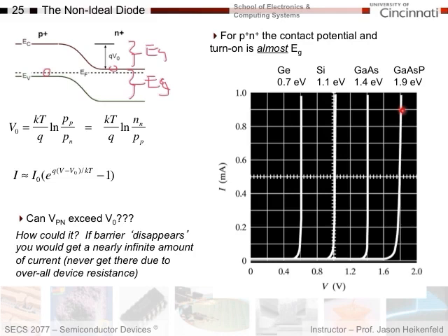And so this shows you, with real data, how when you dope a diode heavily, the threshold to turn it on increases out to the contact potential. So that's important when you go into the lab and you're like, well, why does my ideal diode equation not work? That's because you've got to substitute in the contact potential if you want to make it work as predicted.